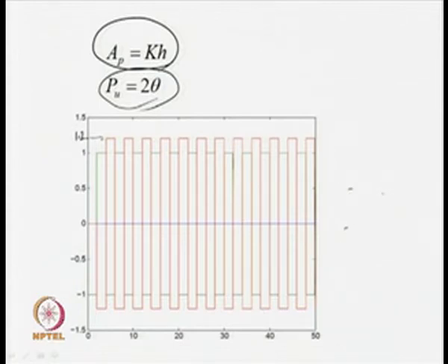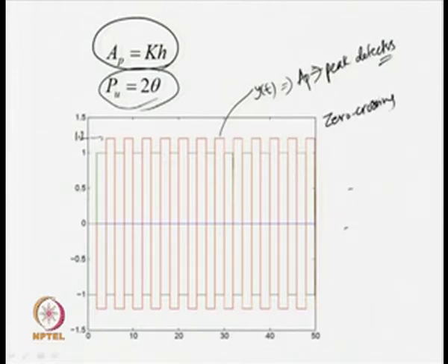If someone takes a measurement of the output of the system y(t), the peak value of the output, designated as A p, can easily be obtained using peak detectors. So, using peak detectors, measure the peak of the output signal, and using zero crossing detectors, it is possible to locate the zero crossings and then measure the span between these zero crossings.